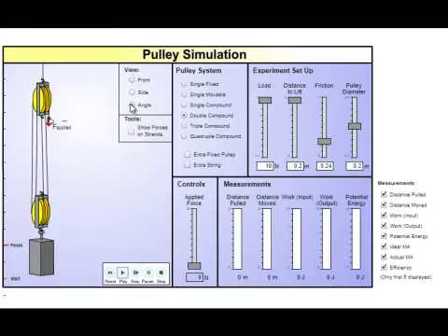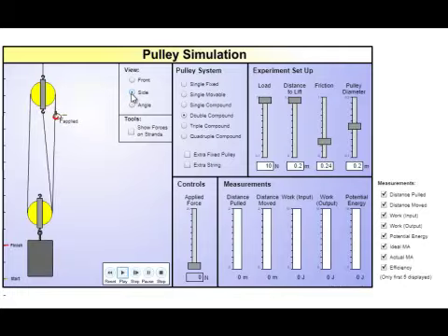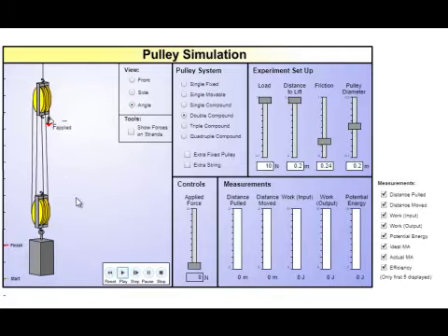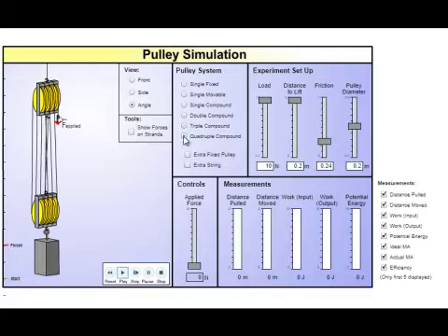Anyway, we could also look at it from the side or the front, but I actually do want to look at it from an angle because here I can definitely see it has 4 segment lines. On a side view, actually 2 of them overlap, so it's hard to see, right? Also, we have 4 segment lines, and later for the triple compound, we have 6, and then for the quadruple, we're going to have 8. And if you count them, it is 8. And of course, this one that you pull on here doesn't count for the segment lines because that's the hauling line. Let me go back to the double compound.